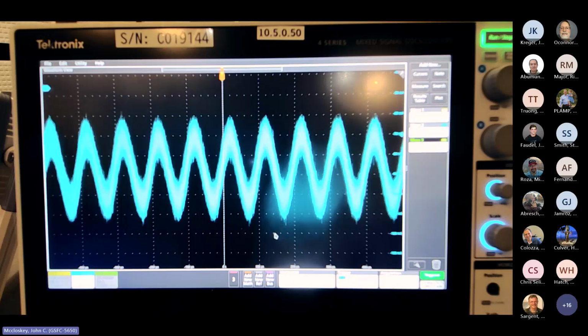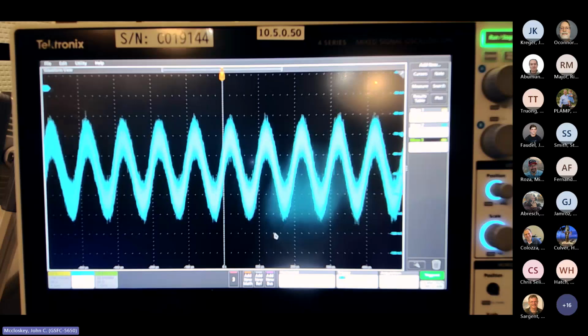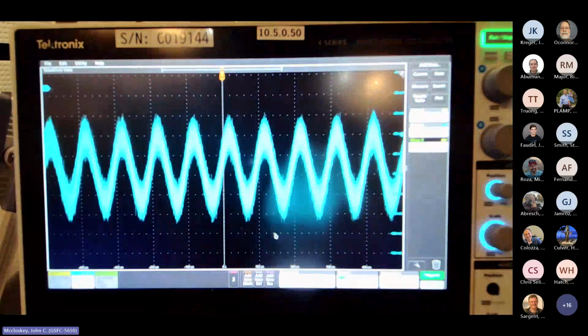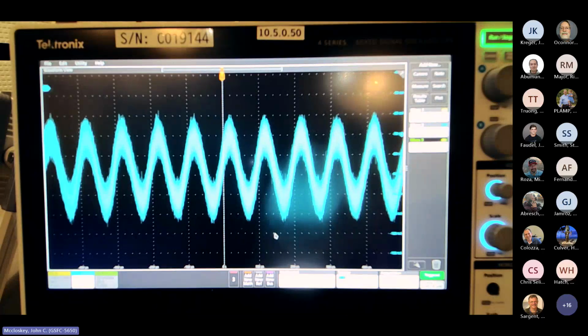For what we're doing here, just playing back the levels into a short circuit, we would expect about three times that, because of the 50 ohm source impedance into the 100 ohm fixture. What we're actually measuring is about 11.8 milliamps. That's right in line with what I measured on Monday, 11.5.